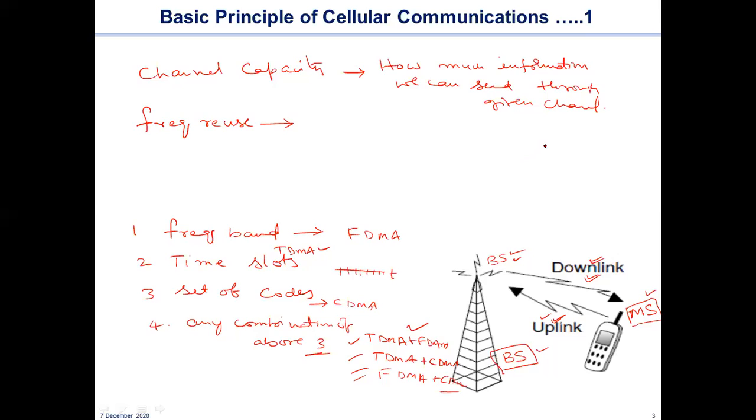Okay, generally we use a cell instead of a circle. We use this hexagonal shape like this. Okay, not square, not circle, hexagonal shape. So these hexagonal cells cover a whole area without overlapping in any geographic area. That is the reason for using the hexagonal shape.